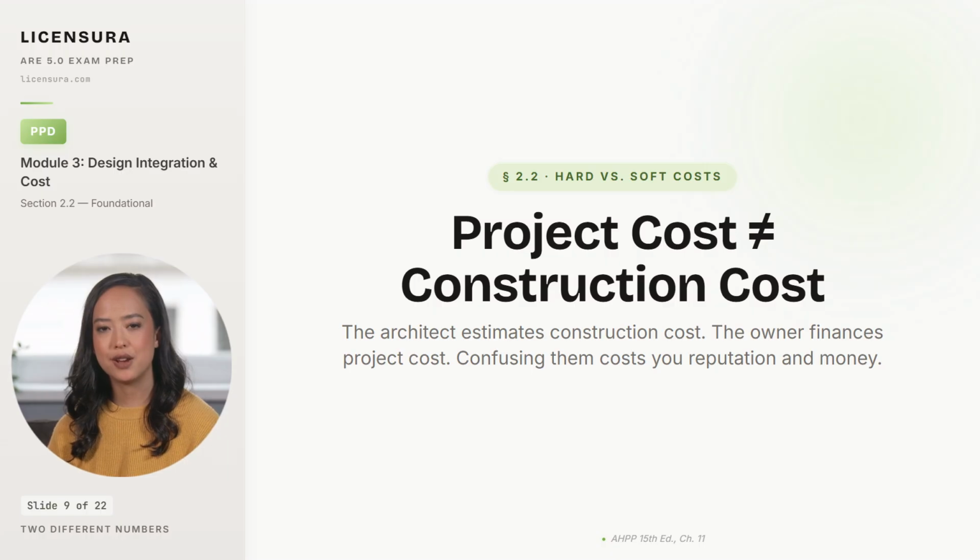Here is the cost language trap most architects fall into the first time they talk to a developer or an institutional owner. You proudly quote a construction cost estimate of $45 million. The owner says the project budget is $52 million. You think you are $7 million under, and the owner thinks you are $5 million over, because their $52 million is the total project cost, while your $45 million is only the hard cost construction piece.